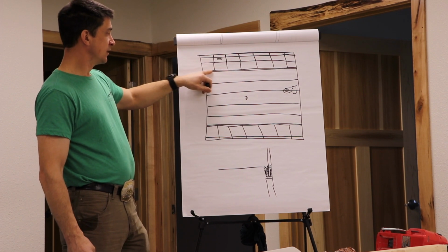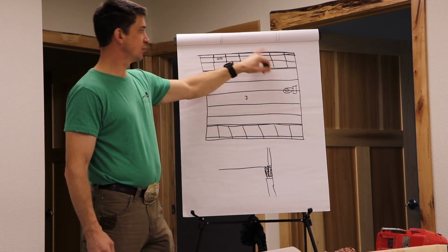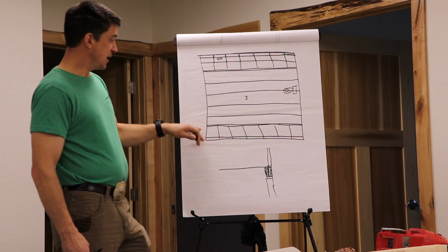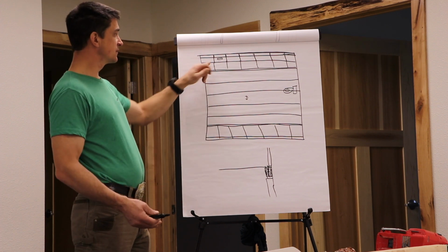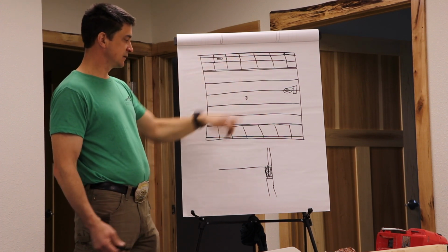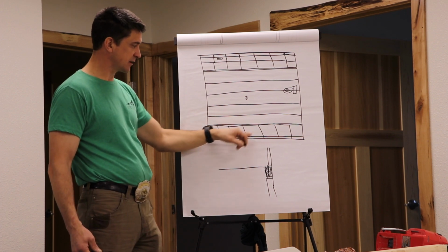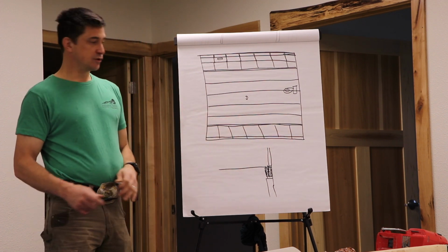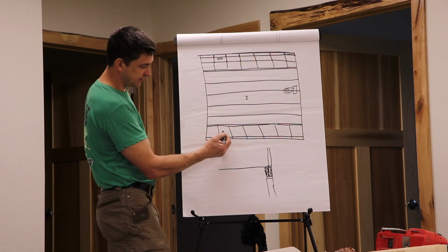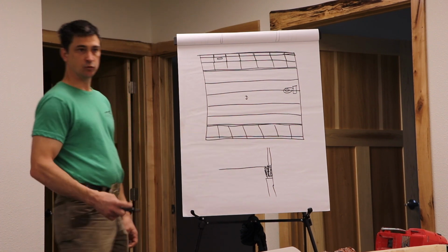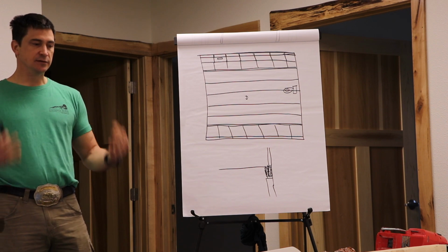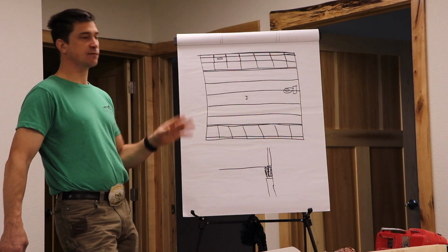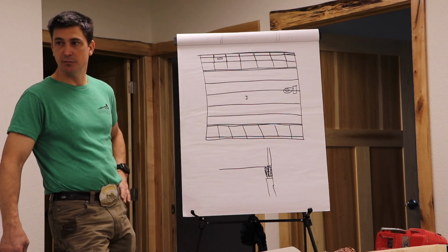So, if we came over 32 inches and doubled this and then put our blocks like that, it'd make access easy for everybody. And so, at the very least, we need to do it with our 14-inch blocks, and over here, even if these are a 20-inch block, we can do that without even having to double this up, okay? But you should never, ever, ever have closer than 12 inches from the outside one, okay? It has to be at least 12 inches away. Otherwise, you've made the entire project a royal pain for every single person that's going to work on that job, okay?